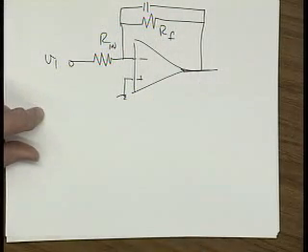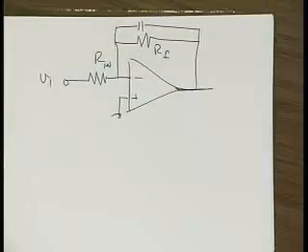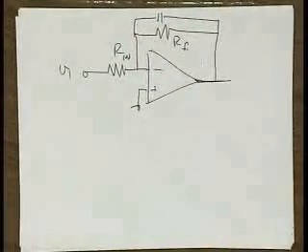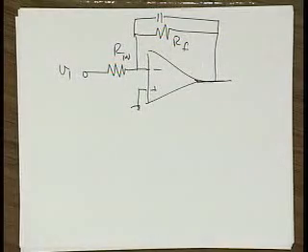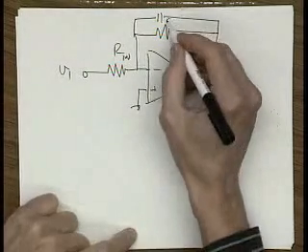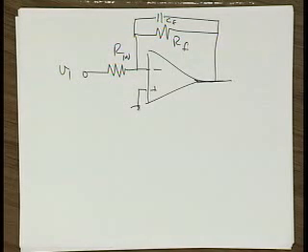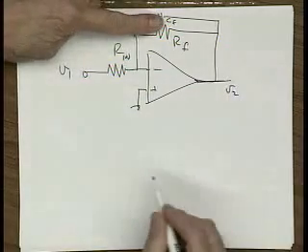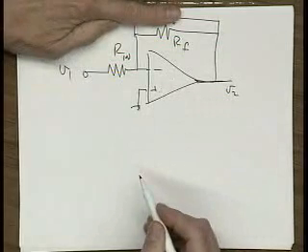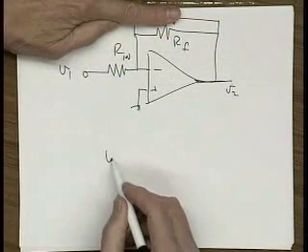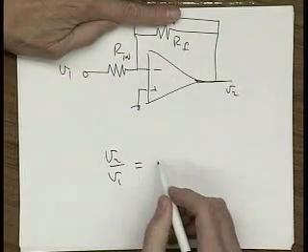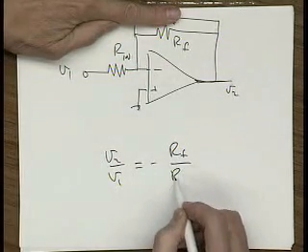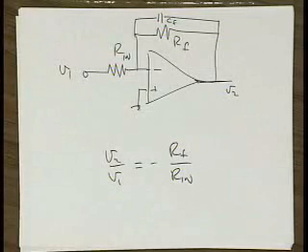Okay? So can you tell me, just sort of intuitively, what's going to happen with this circuit as I go up in frequency? This is CF. Any ideas? What's going to happen as we go higher and higher in frequency? What's the gain of this? Before I put the capacitor there, what is the gain of this circuit? V2 over V1, you should know now, is minus RF over RN. Okay? So now what's going to happen to this circuit as we go up in frequency?